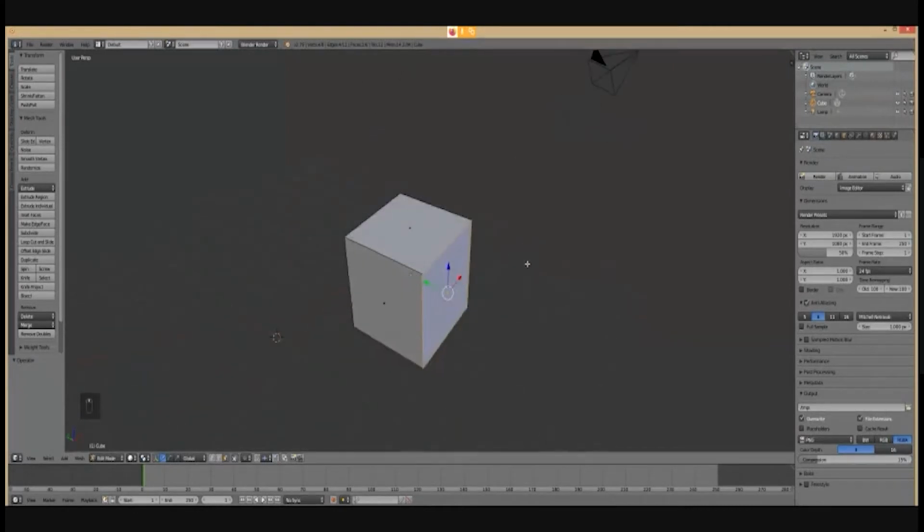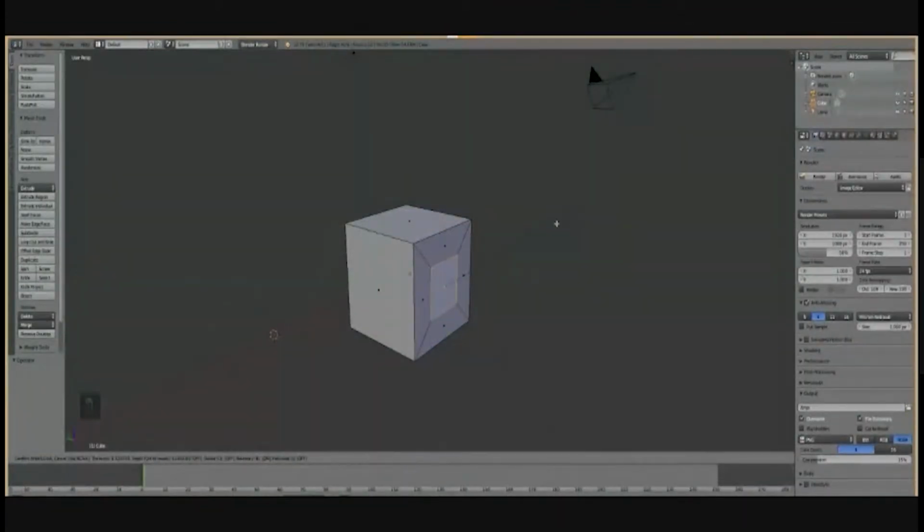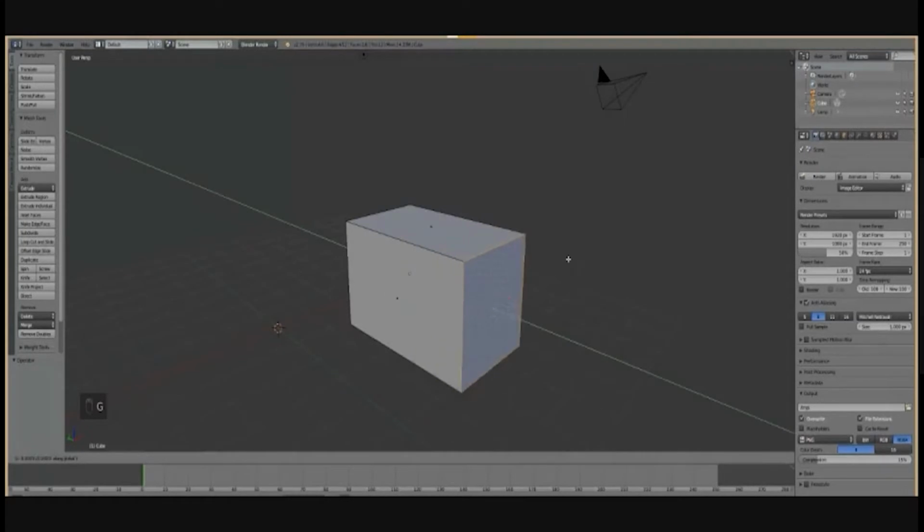The other one is called inset or insert face. I'm not sure of the technical word for it, but basically the shortcut for that on your keyboard is I, right? If you press I, you can do this. So over here, you're essentially creating a face within a face, you can say, right? So again, very helpful. Let me sort of explain. If I click on I, I get this, and then this face again, I can move out or I can move in.